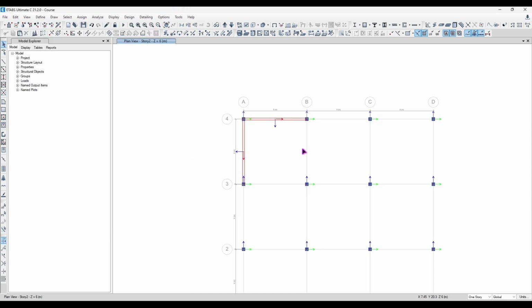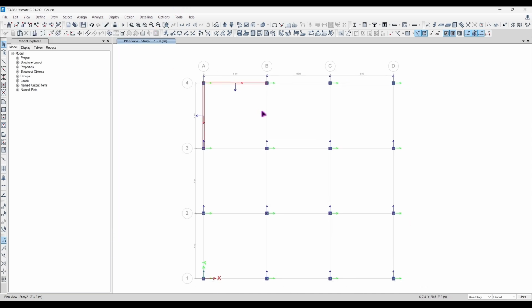So the direction of how you're drawing your walls is really important, and I would prefer that you fix a direction that you draw your walls from. So let's say from down to top and from left to right, or from top to down and from left to right, whatever directions you would like, but just fix it so you don't face any kind of trouble calculating the moment around any of the axes, because of course it's different. So good thing, as you can see here, that all of my columns have the same orientation, so I wouldn't really be concerned about changing anything with my calculations.